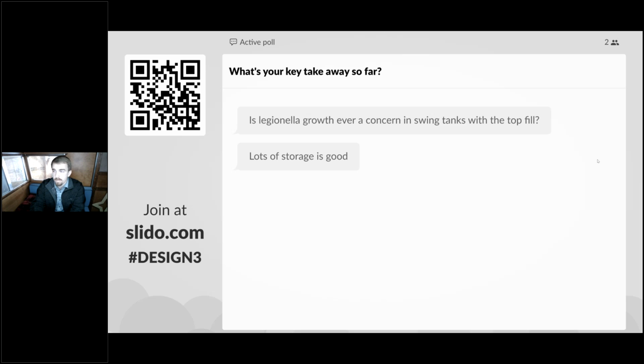Hey Evan, we actually got a question. What temp do you deliver the water at? And say you have 3 storage tanks, what temp would you set the temperature sensor at? That's from Jack. Yeah, great question. Usually it depends on the manufacturer again. CO2, for example, and I think even Mitsubishi, they like a higher storage temperature. CO2 specifically 149. So that's what we would set the temperature to that we deliver to the storage.